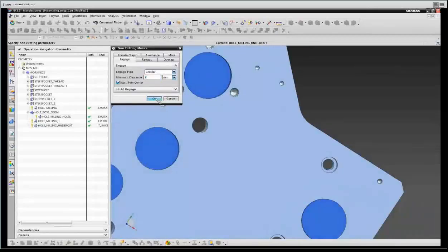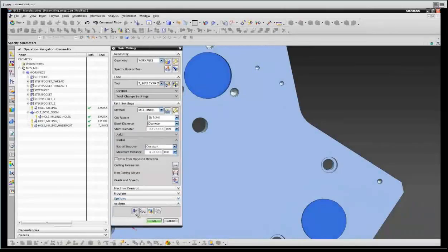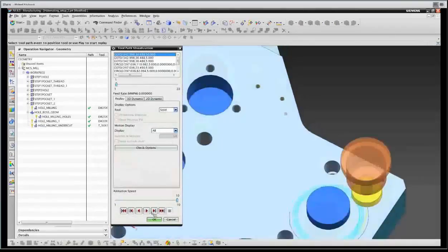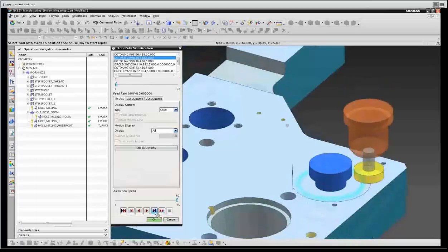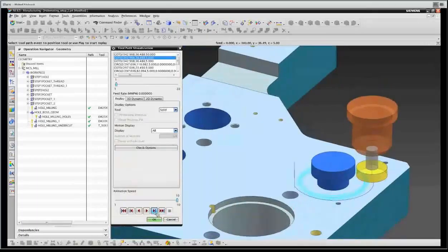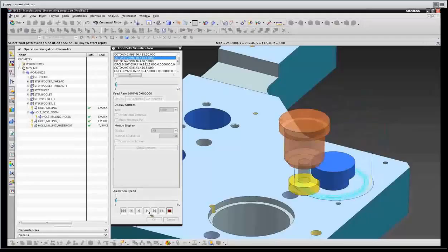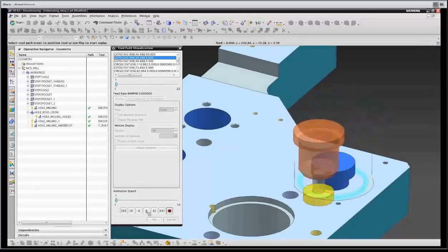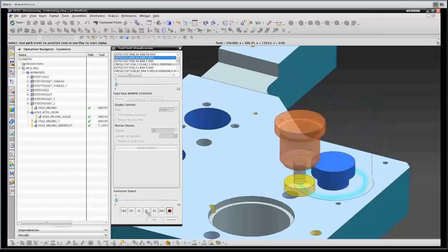You can see we're quite a bit further off the part now, clearance away from the part itself, as we start that motion going. This will just be a pure spiral in and then finish up with one full arc around the inside. So it just walks around and around the part, getting closer and closer with a constant 2 millimeter step over, and then it's going to reposition and come back and cut the bottom one on there. It recognizes the part, knows to stay off of it and not hit what's declared as part geometry.